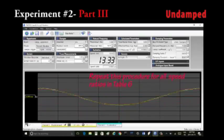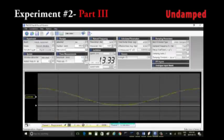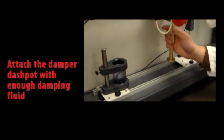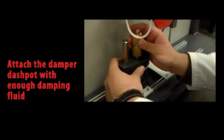Notes: you can change Channel 1 displacement to measure the amplitude properly. The phase lag can be found by measuring the distance between the x-axis cursor at x equals 0 and the x-axis cursor at the first peak. Now, attach the damper dashpot and adjust the piston disc to the fully open position for the lowest damping coefficient.